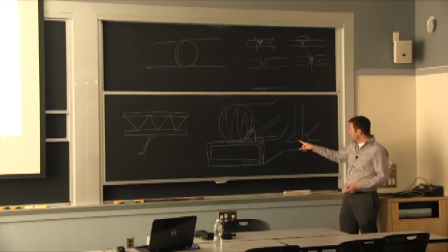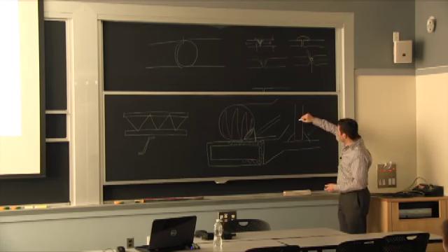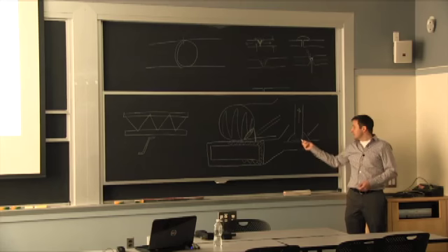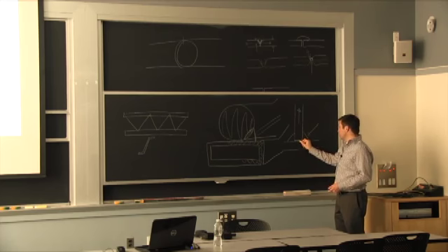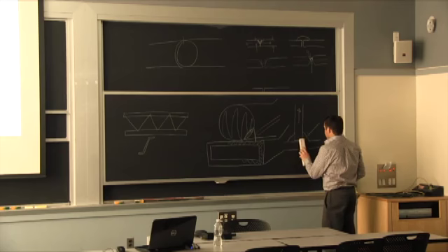It doesn't mean I'm going to penetrate all the way in there, and therefore if I have a pull force here in this direction, I can still be weaker than just having a real T. If I was to forge a real T, this is the area I would have to transfer the load from this component to this one. Well, this is likely to be stronger in fatigue than having twice the interface.